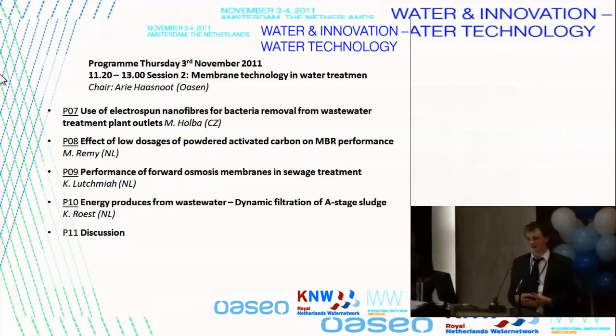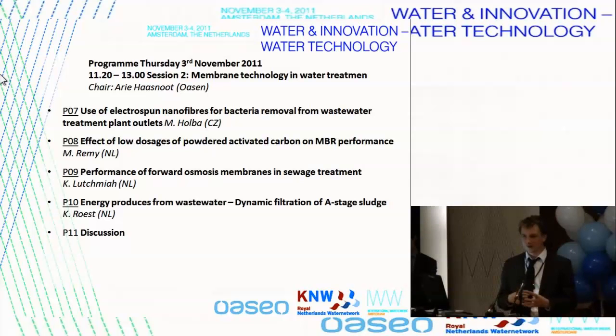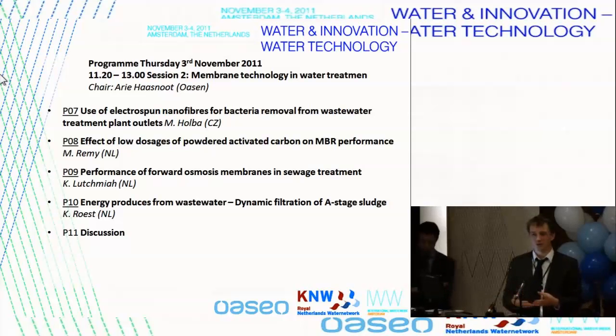Because the idea is that thanks to this activated carbon, you get some stronger flocs, and then for the salt, instead of relying on multivalent cations to make the floc bridges, you do have another way of creating your flocs. We found also the sludge to be more hydrophobic, so you do have some other flocculation mechanisms which make the flocculation less sensitive to the salt. And for the temperature, it is also something to do with the stronger, more compact flocs.